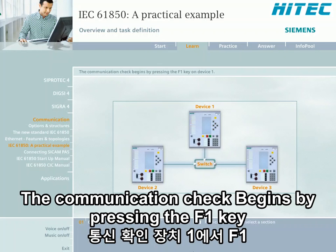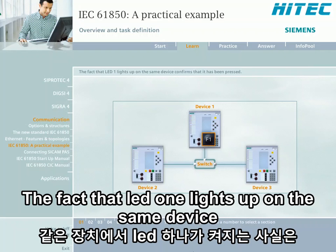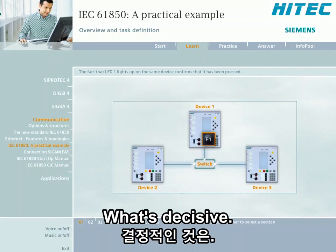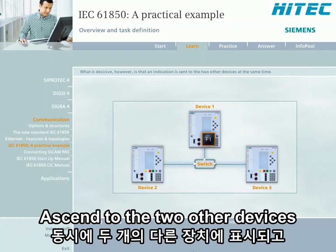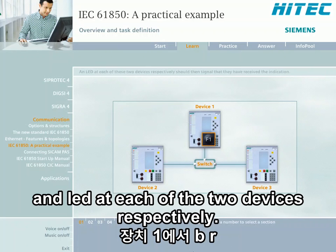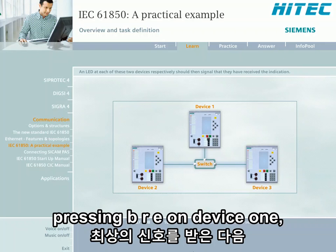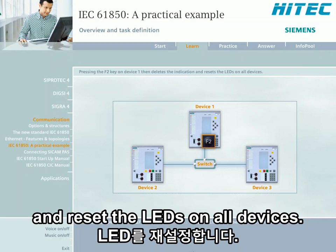The communication check begins by pressing the F1 key on device 1. The fact that LED 1 lights up on the same device confirms that it has been pressed. What's decisive, however, is that an indication is sent to the 2 other devices at the same time. An LED at each of the two devices respectively should then signal that they have received the indication. Pressing the F2 key on device 1 then deletes the indication and resets the LEDs on all devices.